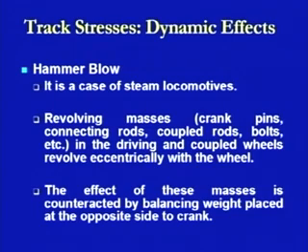Another aspect is hammer blow. This is a case mainly in the steam locomotives. What happens in the steam locomotives is that there are certain revolving masses: crank pins, connecting rods, coupled rods, bolts, etc., and they are provided with the driving and the coupled wheels. When they revolve, a certain amount of eccentricity is caused at that wheel section, and the effect of these masses is counteracted by certain balancing weights which are placed at the opposite side to the crank.